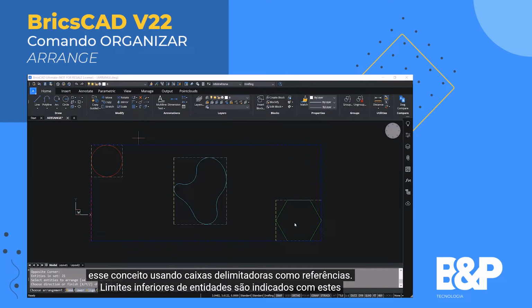Lower bounds of entities are indicated with these yellow dashed edges, and the lower bound of the selection set is indicated with this magenta dashed edge. When you execute lower align, the lower bounds of the entities will get aligned with the lower bound of the selection set, because the lower bound is defined by the smallest coordinate in the X direction.